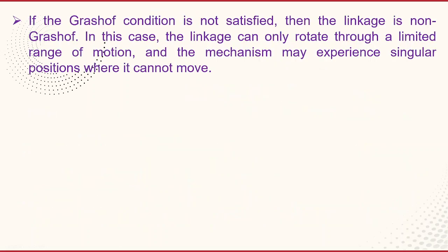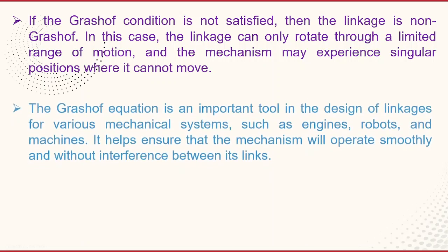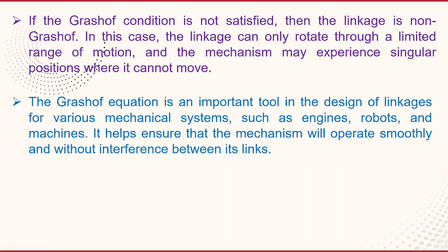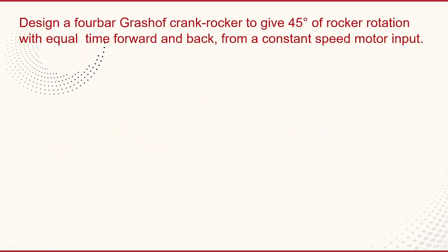If the Grashof condition is not satisfied, then the linkage is non-Grashof. In this case, the linkage can only rotate through a limited range of motion and the mechanism may experience singular positions where it cannot move. The Grashof equation is an important tool in the design of linkages for various mechanical systems such as engines, robots, and machines. It helps ensure that the mechanism will operate smoothly and without interference between its links.